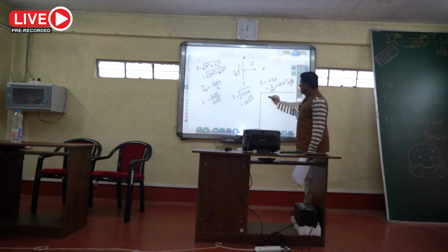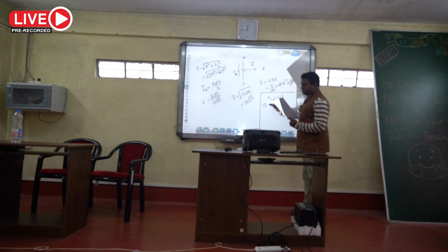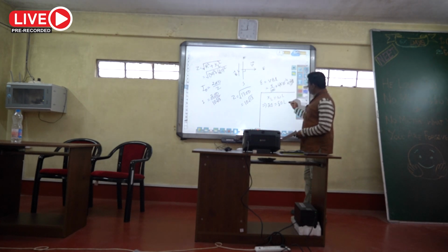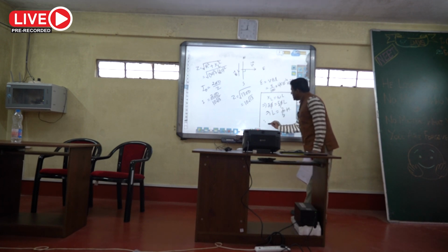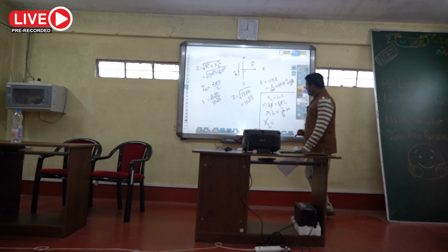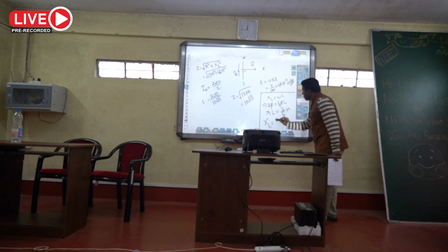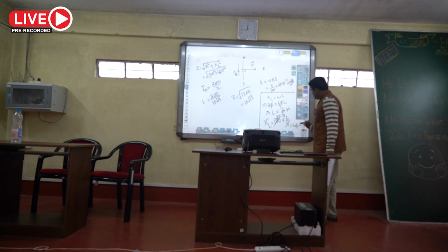So first we have to find L, XL equal to omega L. So XL is given 20 equal to omega is 50, then L we have to find out. So L equal to 2 by 5 Henry, right. Then finally XL prime, suppose, that we have to calculate, that is omega L. Omega is now 100 into 2 by 5. That is 40 ohm.